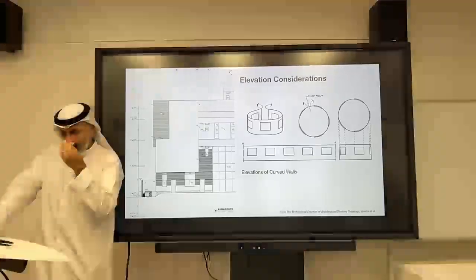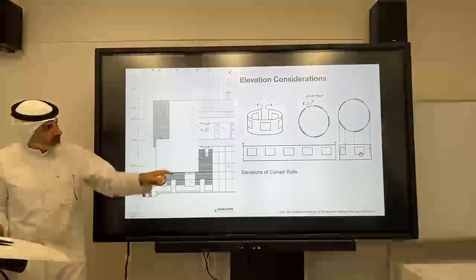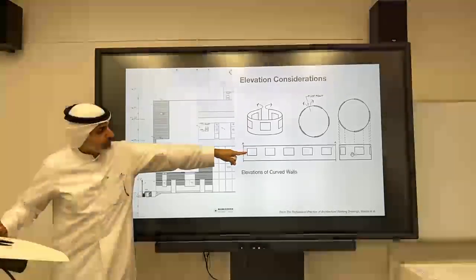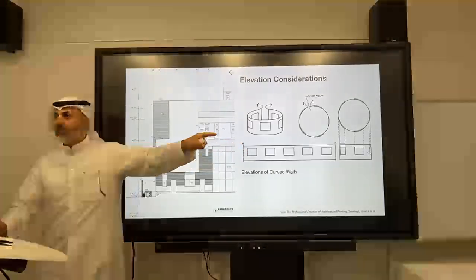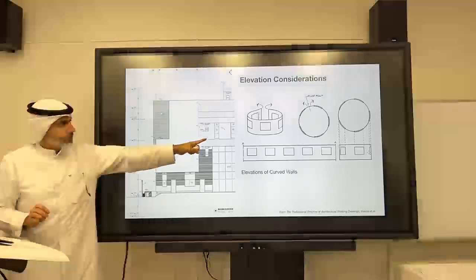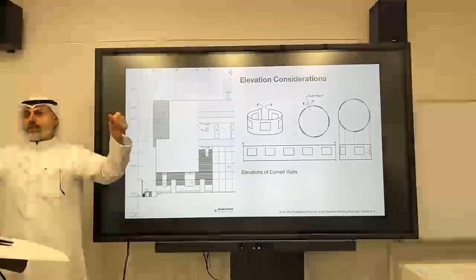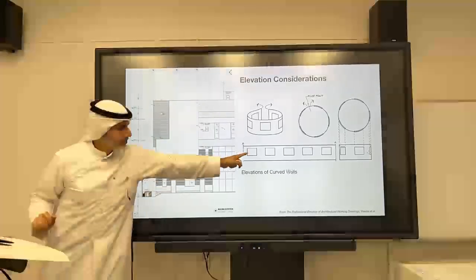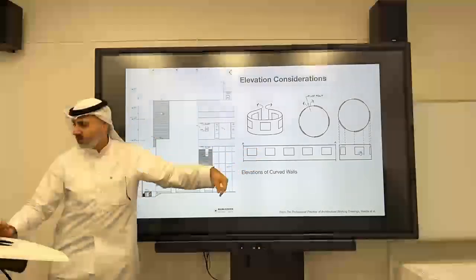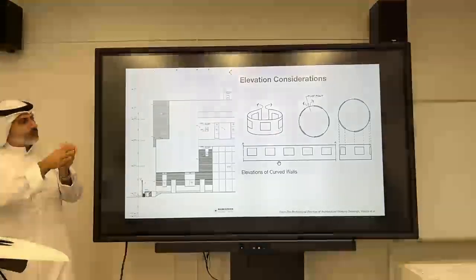If you have a curved wall, for construction purposes, this doesn't help much. When we show it actually as is, you see how it's distorted. One time the window looks big, one time it looks small, one time it shows just part of it. So for construction purposes, you need to unpeel the elevation like you see here, so that you can see it as a straight elevation, and the measurements are actual. So I know between one window and the next, say, one meter, whereas here this distance is different than this distance because it's angled. So that's typically what they do when it's a curved wall.